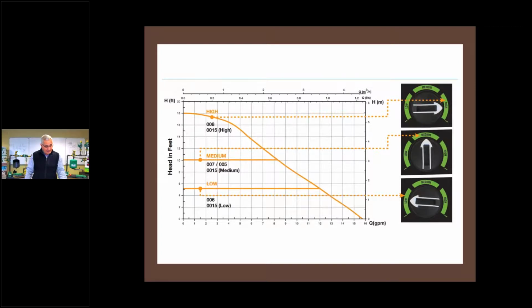And then the last zone, the black zone, at 0.8 at 2 feet of head. Well, guys, we're down here. 0.8, I'm just past that hash mark. 2 feet of head is here. I'm going to set it at low. We'll end up performing about right there at the 5 foot head mark. Again, probably pumping 1 GPM more than I need. Again, I'll be squeezing my delta. But I'm still as close as could be.